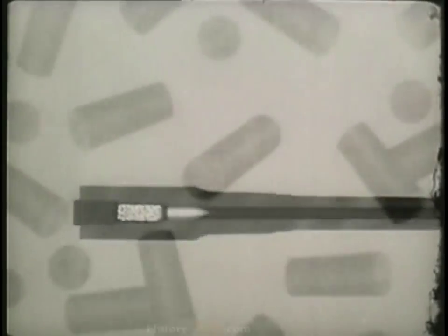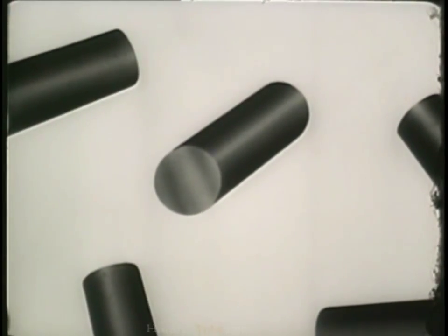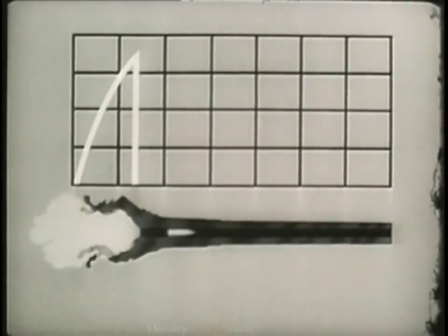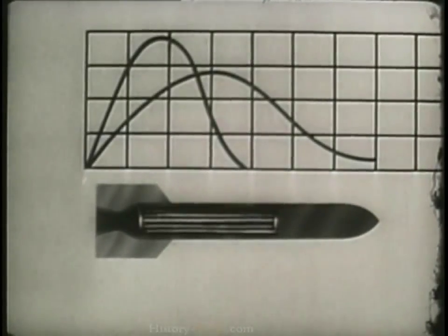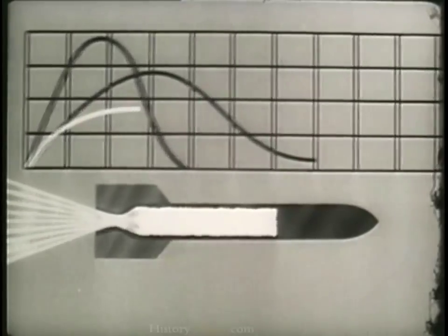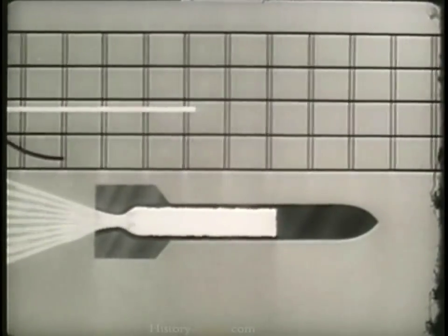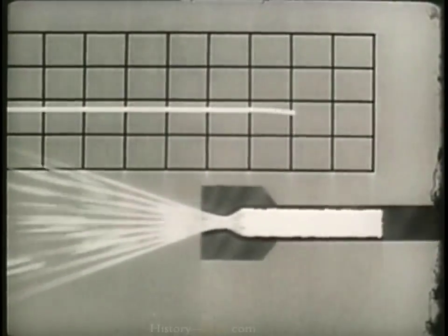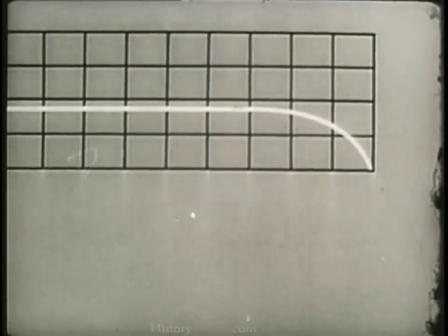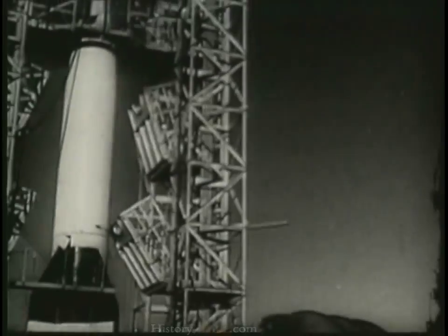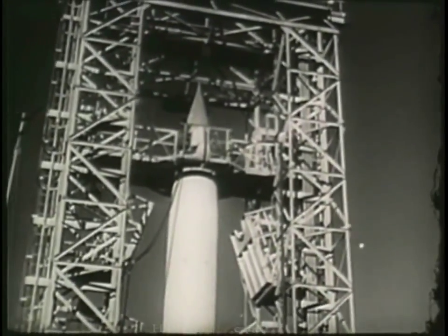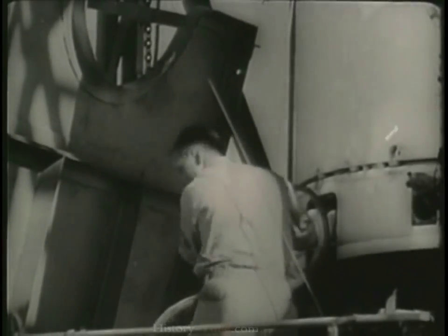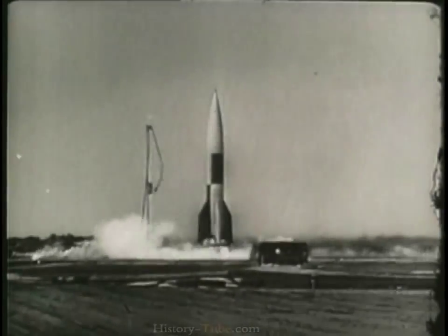But if we use digressive grains in a long-barreled gun, there's a chance that the higher maximum pressure produced will blow it up. For a rocket, we need a low, steady pressure, so we use a special neutral grain. The low pressure will not burst the lightweight rocket, yet gives smooth acceleration. For the V2 and other large rockets, it's better to use certain liquid propellants, mixing them at a constant rate to assure constant burning.